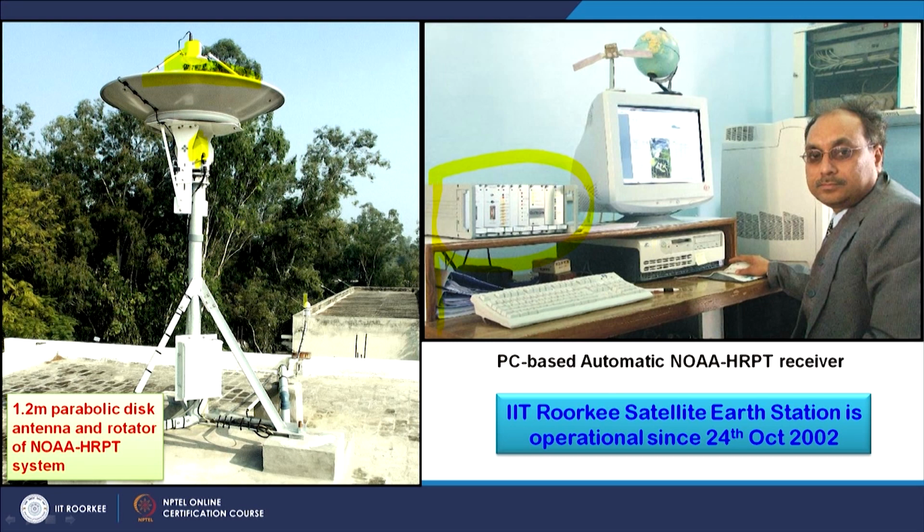One more important thing is the other antenna which you can see here, the GPS antenna. So, there are two antennas outside and the rest of the things are inside. Why this GPS antenna or GNSS antenna? There are two purposes. One is to determine the location of this antenna on the globe, and the second is to provide accurate timing to this receiving PC or computer.